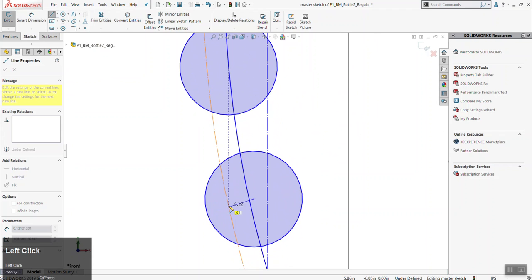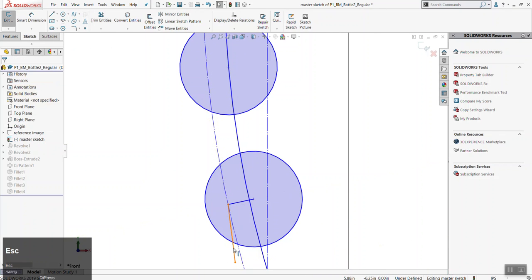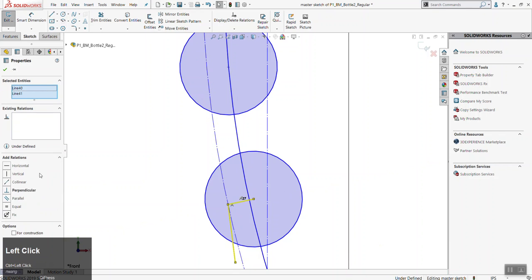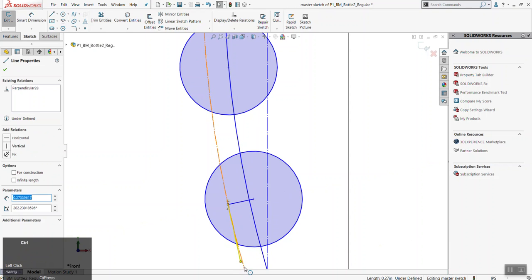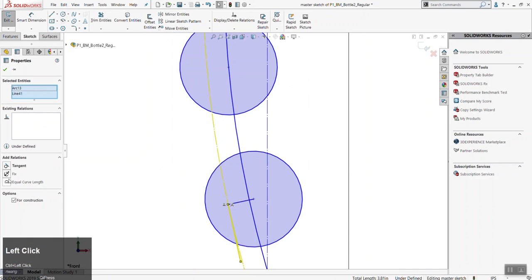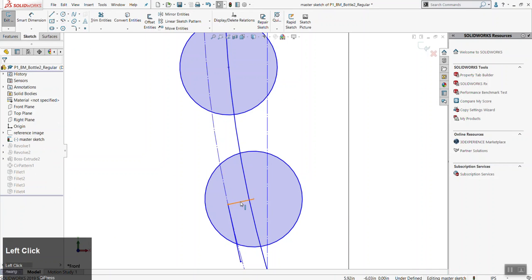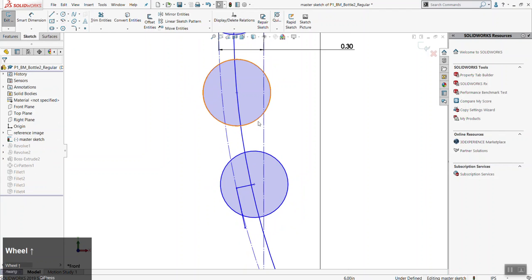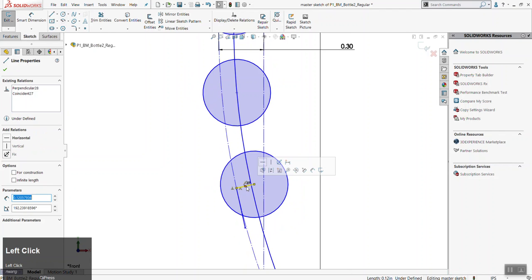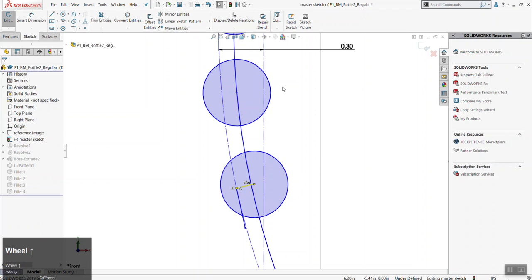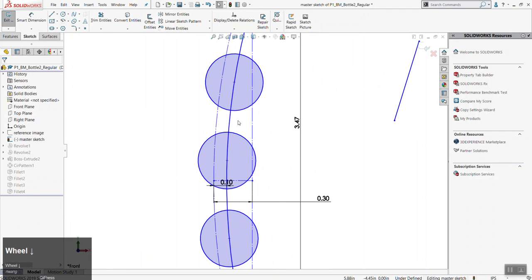If you go this route, I would also have a line coming here. This is what construction lines are used for. So like this is perpendicular. You would then set this to be tangent. I realize again that this is pretty convoluted, but if you set this up for each circle and set all of these lengths to be equal and define one of them, you define it. I think this offset is the way that I would prefer to do it.